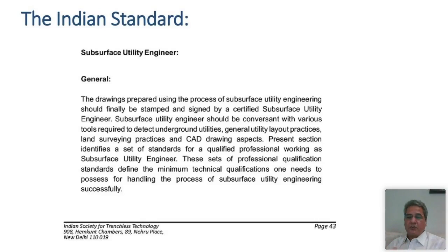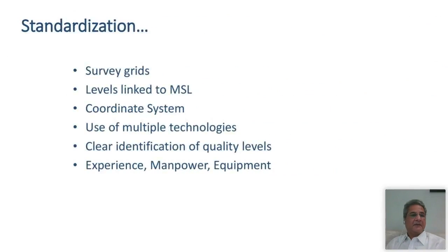So very soon, most of the departments or organizations are going to make it mandatory that each underground utility drawing should be stamped by a certified subsurface utility engineer. We are in the process of creating these engineers. Already India has more than 100 engineers certified. Standardization is in terms of survey grids, level linked to MSL, coordinate system, use of multiple technologies, clear identification of quality levels, experience, manpower, and equipment.